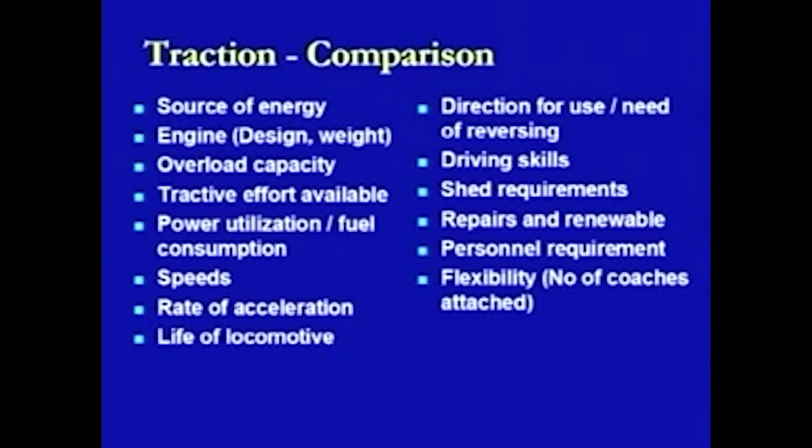The flexibility, here, is being defined in terms of the number of coaches which can be attached to the same locomotive. Today we are running 18 to 24 coaches with one locomotive. If there is an emergency and there is a need of incorporating some more coaches between two points, that is the origin and destination, that flexibility is there more in the case of electrified locomotives as compared to the diesel locomotives. This is because there is a possibility of installing some more power unit on the same locomotive, as compared to the diesel locomotive, where another locomotive is to be used if more coaches are being attached.